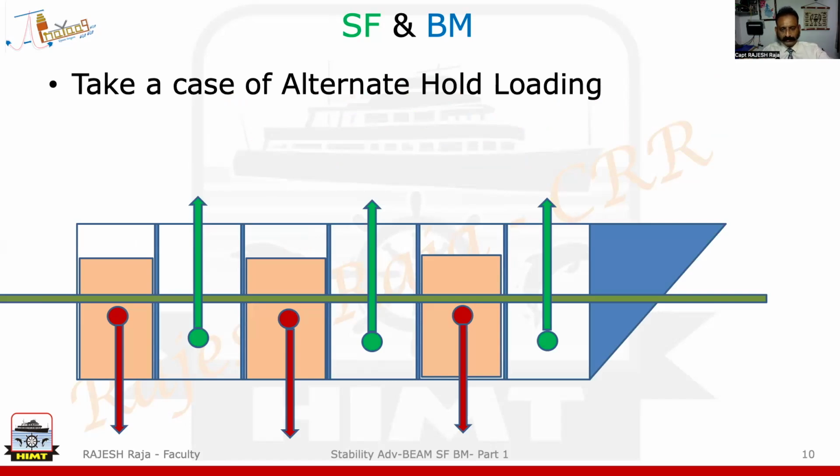Now similarly, I've shown you the force of buoyancy acting quite strongly at the empty holds. Even though in the filled holds also, on the underwater volume which the filled holds have outside, they also have force of buoyancy. But you will see they will act more on this empty space. Why? Because there's nothing to cancel here.